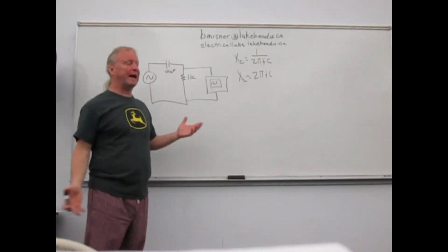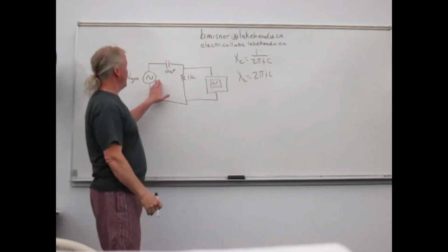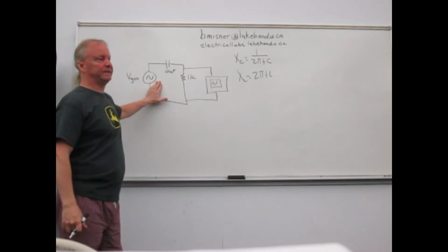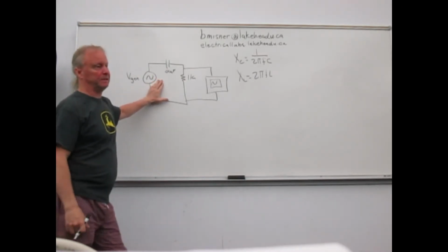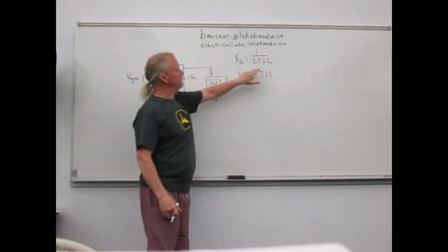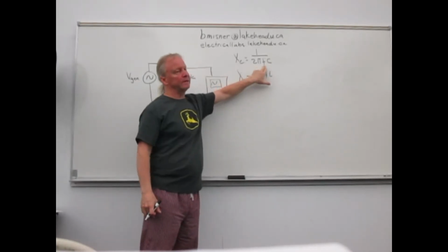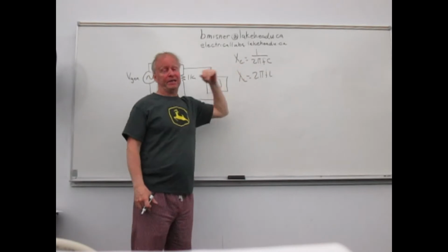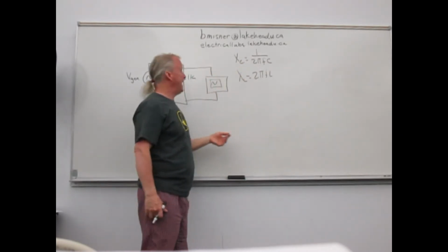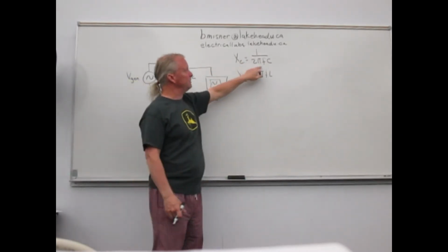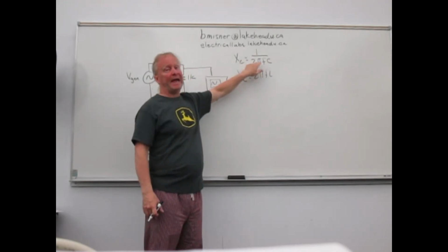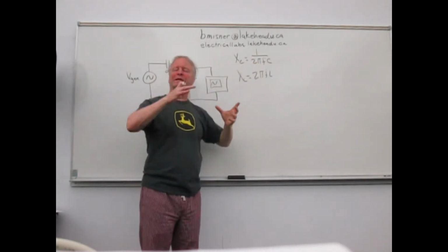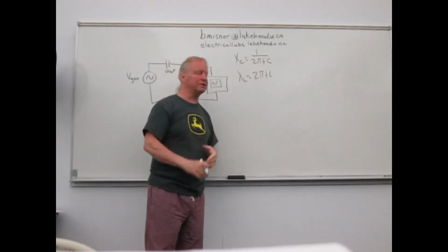Okay? So now, when we start, say, with our frequency at a low frequency, right? So if this C or F is small, then XC is large. And as we increase the frequency, XC gets smaller and smaller, so less voltage is going to be dropped across it.